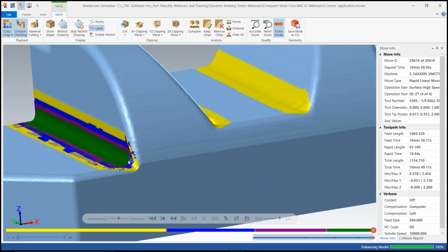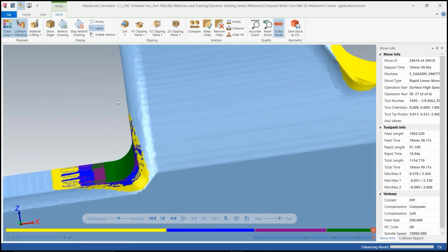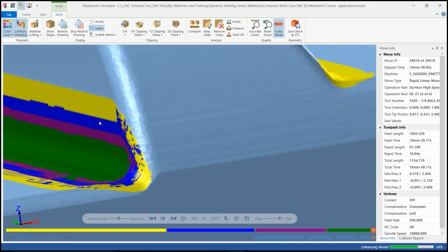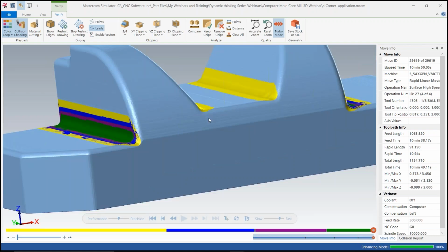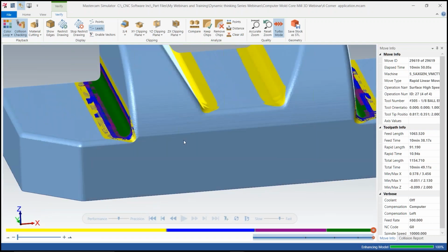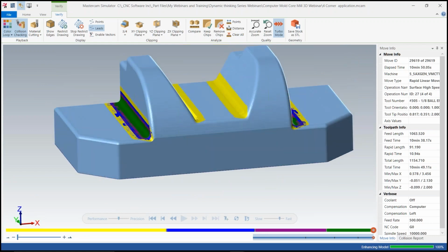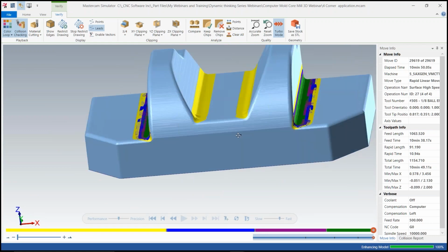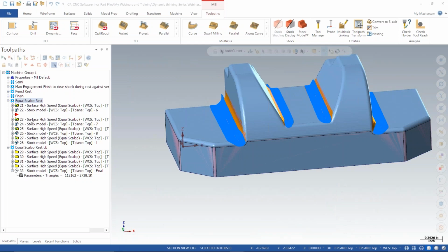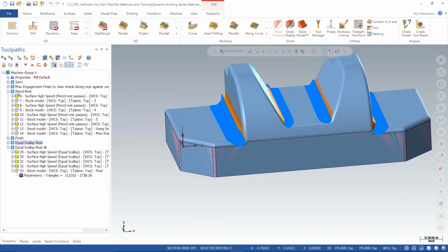And then that part now has a nice consistent skin left on it. I left 7 here, there's 5 here. I could have went to 5 if I wanted to, and it's safe for semi-finishing now. And further finishing if I want. I can semi it again, or I can start to finish it now. So that's one way of digging into a corner. Okay. I call that pencil rest.